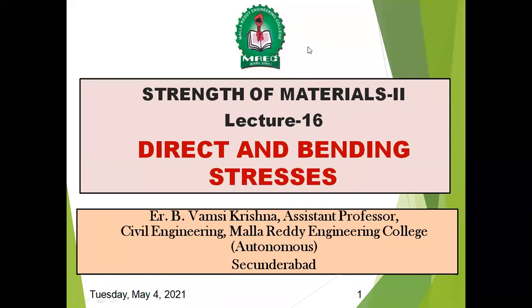Why? Because a column is a vertical member which is subjected to compression force. If you take a column, it will have an axial load. That axial load itself is a direct load. For example, if the load is not at the center, what happens? If the load has some eccentricity, obviously the column will have both direct and bending stresses. That is how in this unit we are going to study in detail the direct and bending stresses acting on columns especially. Understand?